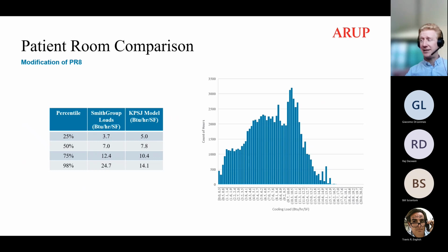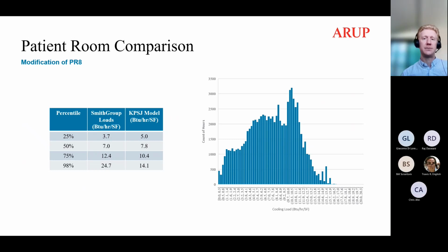So for an individual room, you would not want to use that value. A way you could reconstruct that, you could get the same, I think, resultant distribution, if you were to use a stochastic approach to the energy modeling and say you're going to provide a variety of schedules that are still drawn from that same underlying distribution that do hit those peaks. And then I think you would see that and you'd be able to reconstruct, similarly, what does it look like as an absolute maximum for the patient room? And then separately, what does it look like for the overall system and the diversity in the system? So I think it is a critical distinction, yes, Travis, between what the prior work has looked at, which is cooling load and sizing, and what this is looking at, which is trying to find the same trend for annual energy use for the sake of predicting energy performance and then life cycle cost impacts, et cetera, of system decisions. Okay. Yeah, I got it.